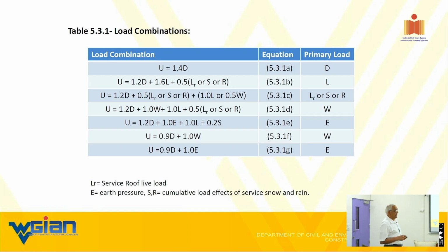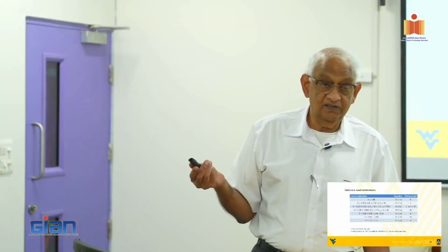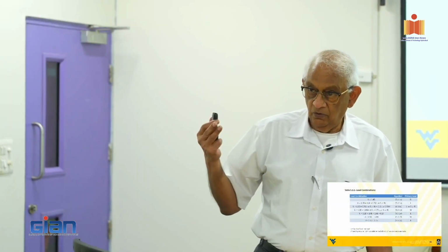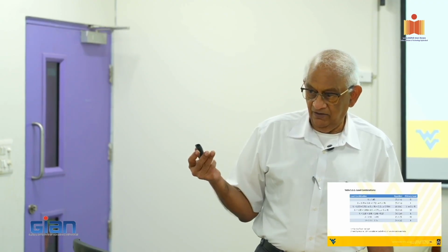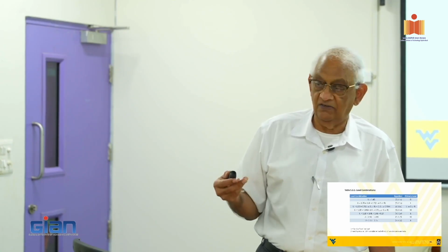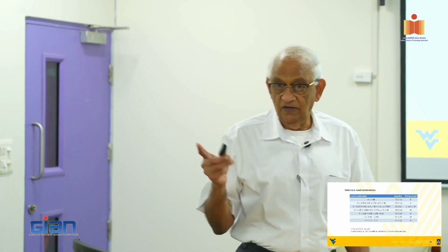Many dissertations were done. All this comes from field evaluation. So they go to 1,000 different slab systems, for example, and measure the thickness, and you say, okay, the max thickness value is 40% higher than called for. 6-inch means sometimes people put 8 inches, sometimes they put 5 inches. That is that bell-shaped curve. So that is where the factors were derived.